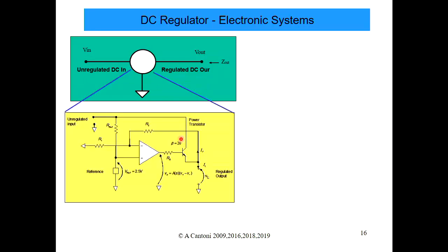So a way to do that is to have some electronic circuit. And in fact, in the exercises online, there is this circuit, and it goes through how you can find the response of such a circuit. The idea of a power supply is really to deliver a constant potential difference at very low impedance. Whenever you take current out of that supply, you don't cause very much of a drop in the output voltage. That's the ideal. The ideal voltage source has zero output impedance, so if you take any current out, it's not going to change the voltage.